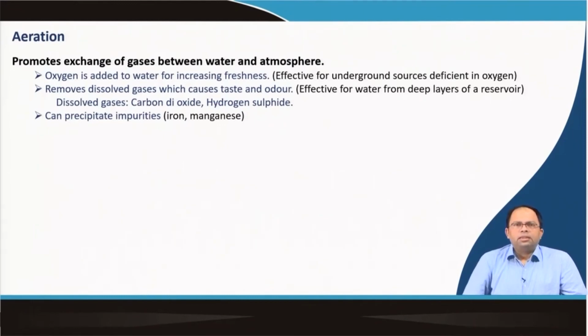Aeration is the process which promotes exchange of gases between the water and the atmosphere. Usually we add oxygen to water, and when we add oxygen, it increases the freshness. It is effective for underground sources, which are deficient in oxygen because they are not in contact with the atmosphere. So, addition of oxygen will improve the freshness of that water.